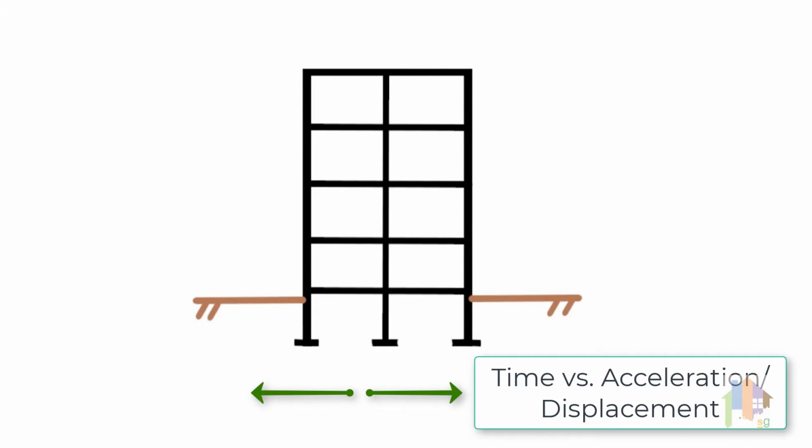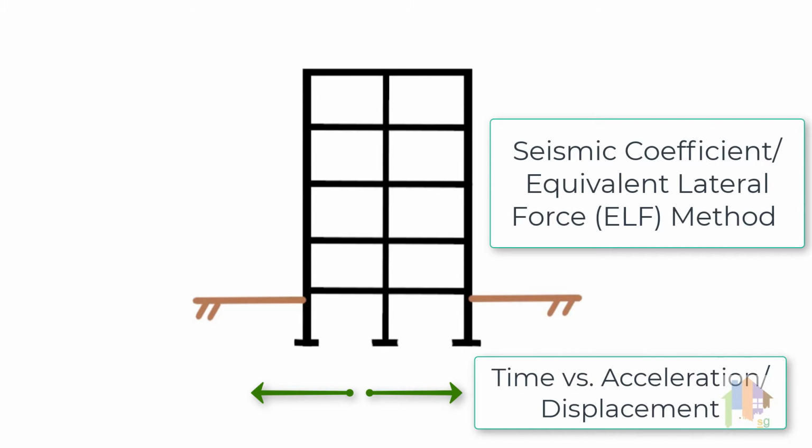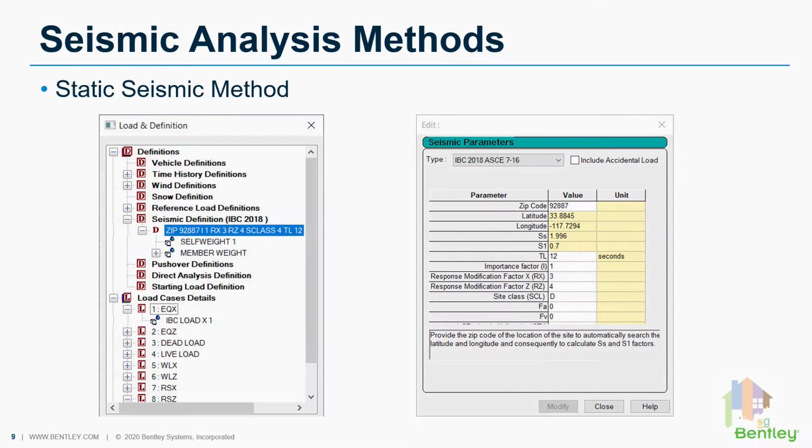That's why seismic analysis is purely a dynamic analysis. At different time intervals, the structure will experience different forces due to variable ground acceleration. For simplicity of calculation, we modify this dynamic loading into static loading. There are several conditions mentioned in relevant codes like ASCE 7, EC 8 or IS 1893 on when to use static seismic load or when to consider the seismic load as dynamic load. I'll discuss this later.